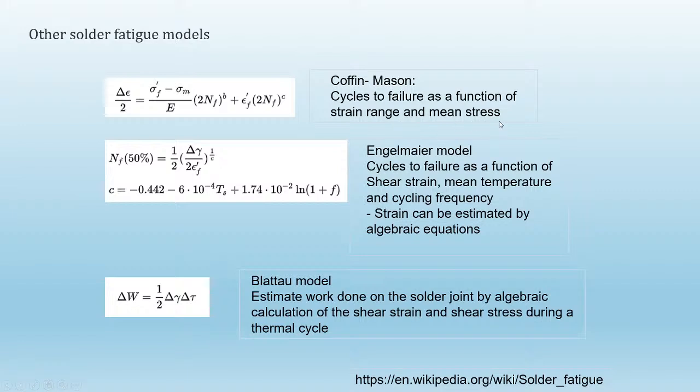So this doesn't include creep, which means you don't have to get the full detailed viscoplasticity model. But obviously, it also means you would have to do this type of correlation yourself, right? You can do a very simple either analytical or simulation data to get strain and stress, and then, if you do enough experiments, you can figure out what all the coefficients are and use that in the future for your fatigue calculation.